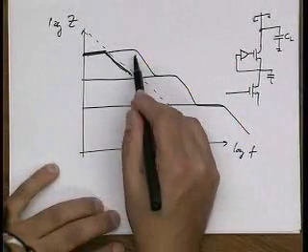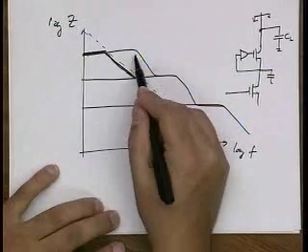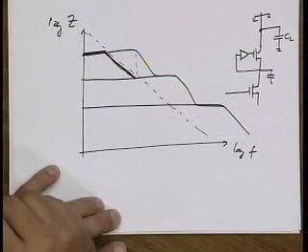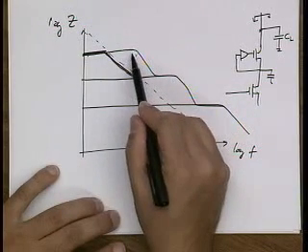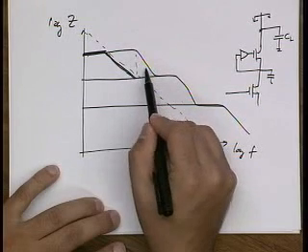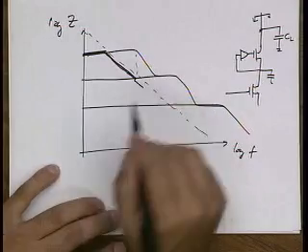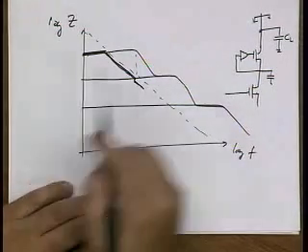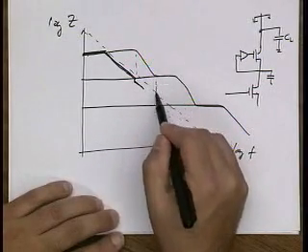And you can see that as I cross this frequency here, for all practical purposes, if I plot this in SPICE, I won't see any change. But if you actually think about what's going on, all of a sudden, this starts dropping, right? So there should be a small shift, a tiny little shift, because now this impedance is dropping too. Same thing over here.